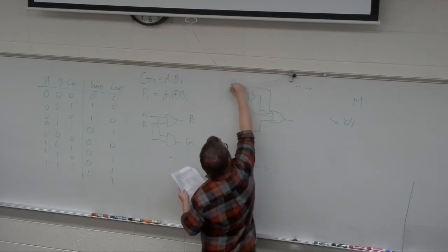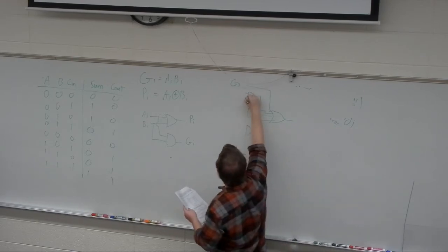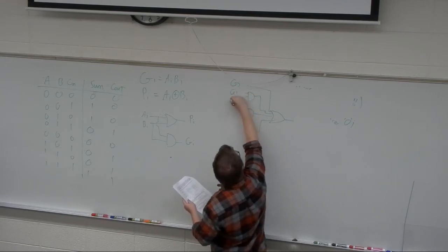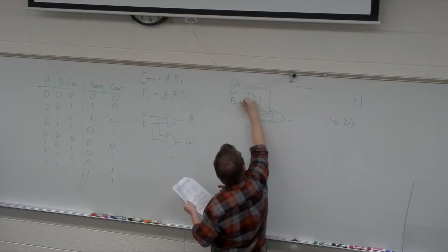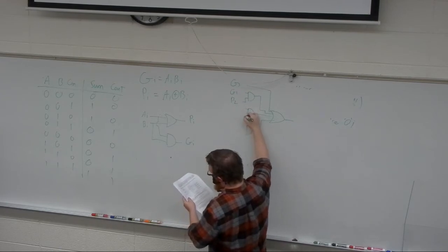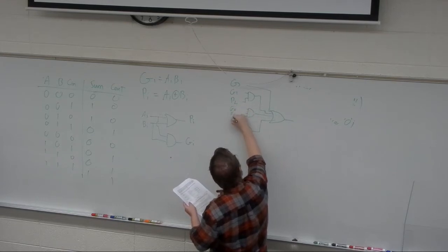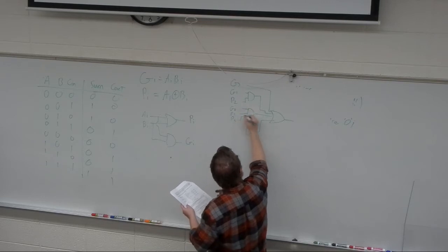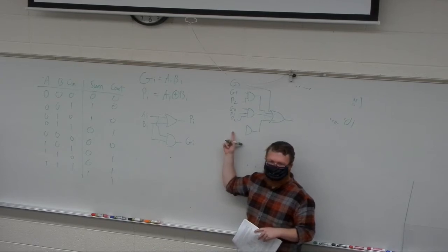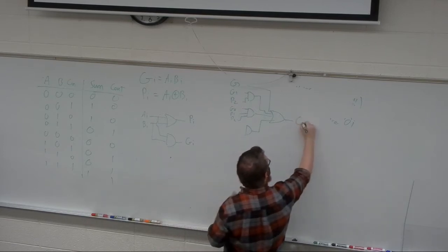Where this is going to be generate 3, right? Because the generate 3 stands on its own from that earlier equation. And then you're going to have the G1 and P2 from the last one. And then you would have G0, P1, P2. And so on and so forth, right? So I'm just implementing those equations earlier in AND and OR gates. And that outputs me with the carry.